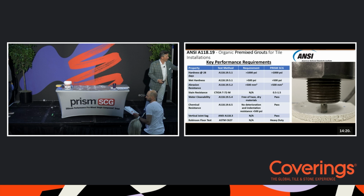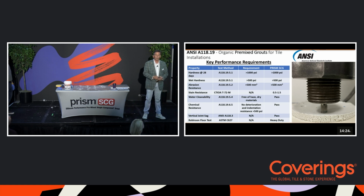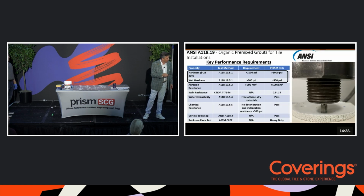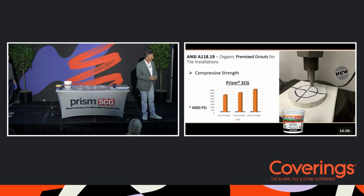So you can see here, these are the performance requirements charts out of ANSI for the premix grout category. And we can see that the PSI for compressive is different than cement or epoxy. It's much lower, from 3,000 to 1,000, right? Well, here's the good news. We know that Prism SCG will exceed 4,000 PSI after 28 days.